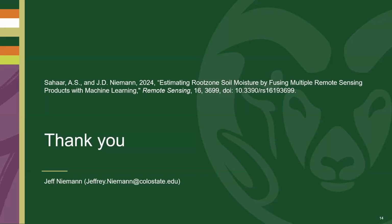All we did is said, if you're within, for example, a SMAP 9-kilometer grid cell, all those 70-meter grid cells get the same value from that SMAP 9-kilometer value. So I'm not saying that we actually achieve a realistic 70-meter resolution on all the inputs. It's just for consistency, we sample everything down to that same spatial resolution.